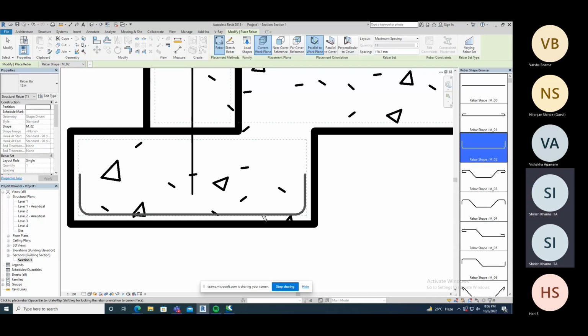When we are placing it now, see, it shows 11 there in the rebar set. Now, I don't want 11, I need a 150 mm gap between them. So 13 are there, see. Click on it so that it is placed. Now see, 13 are placed.